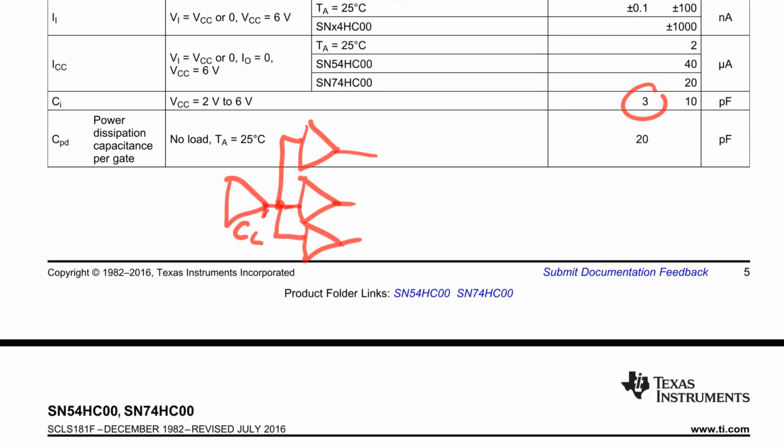So just be aware of that. That can be a big deal. And maximum fan out was a big deal back in the day when they designed computers with 74 series logic, because you'd have one chip driving 20, 30 other chips. And it was a big deal. And capacitance of the input pins really mattered.